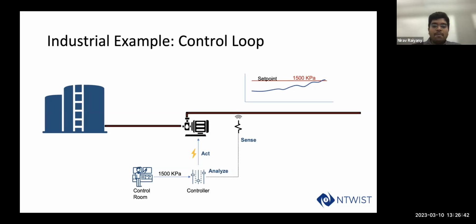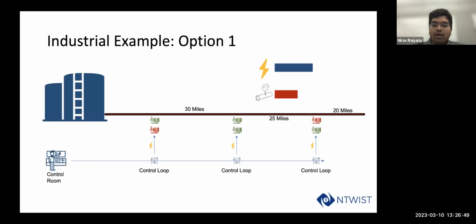However, the interesting part is that when you have this kind of setting where you have lots of pumps, your goal is to achieve some flow rate so you can meet the demand at the receiving end. You can achieve the same flow rate by using multiple settings. So there are multiple ways to achieve the same flow rate. For example, you could probably use just one pump at the first station, then two pumps at the second station and just one pump at the third station. And you would be able to maintain the flow rate of X, say, for this example. Now, another way of achieving the same flow rate would be using two pumps instead of one at the first station and then one pump at the second station, and it's doing the same job.